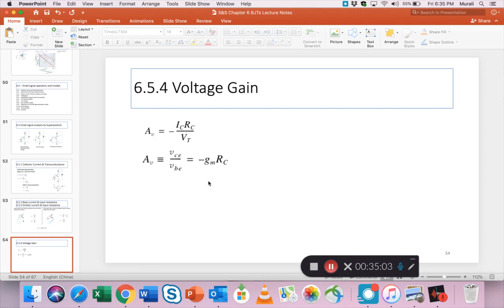As long as you have a transistor amplifier and you can at least calculate the GM very quickly based on the Q point current IC, you can say, yes, whatever signal you put into the base circuit, I can roughly tell you what the output signal will be because the gain is this simple relationship. Okay, so that's the benefit of knowing the voltage gain.